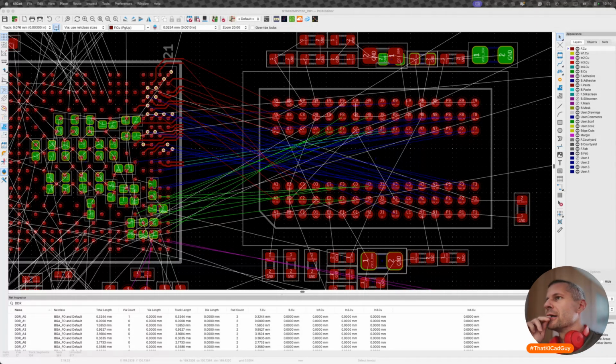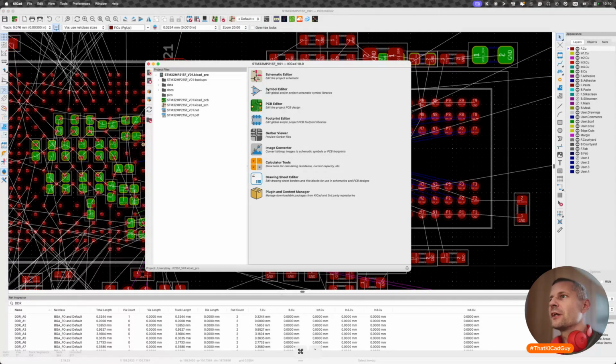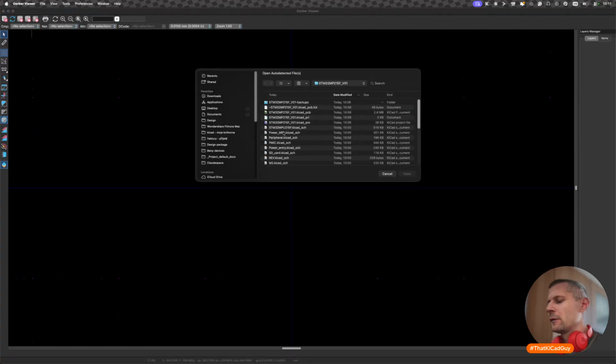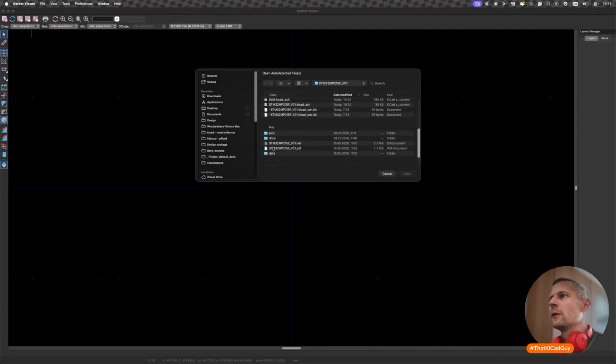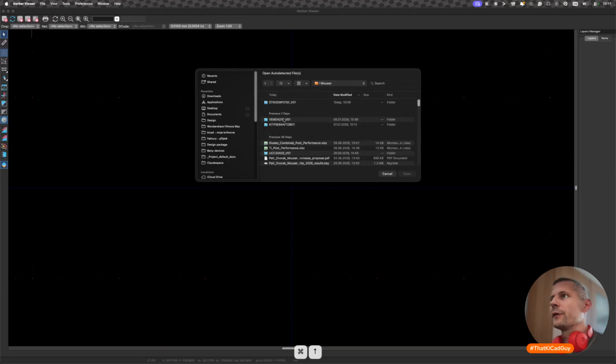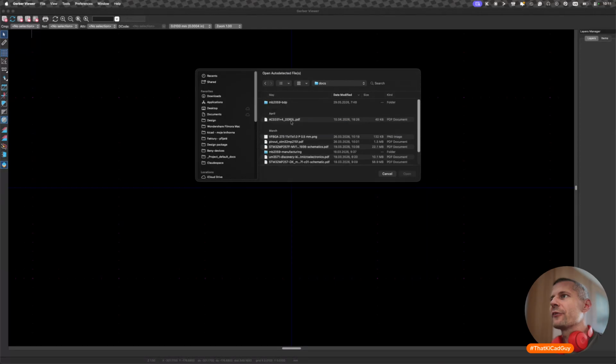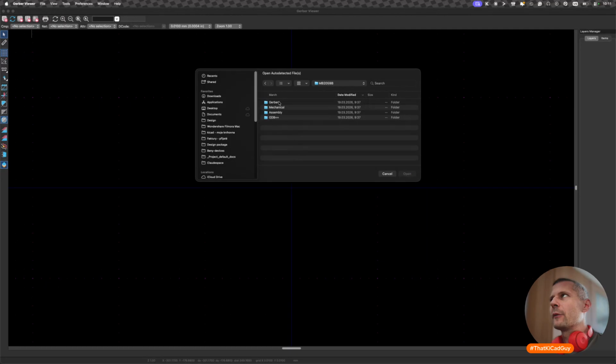Anyway, yes. Back to the signals. Gerbers. We have to see the Gerbers because I want to check how many tracks of the reference design from the upper part of the BGA went to the upper part of the DDR3 and vice versa.